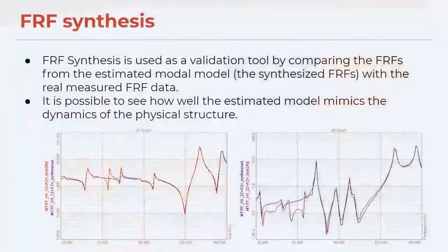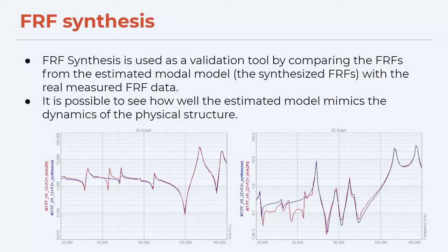The next step is the FRF synthesis, which is used as a validation tool by comparing the FRFs that were measured with the ones synthesized from the estimated model. From this comparison, it is possible to see how well the estimated model mimics the dynamics of the actual physical structure.